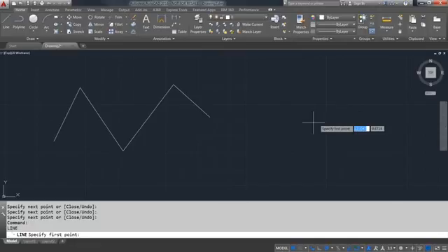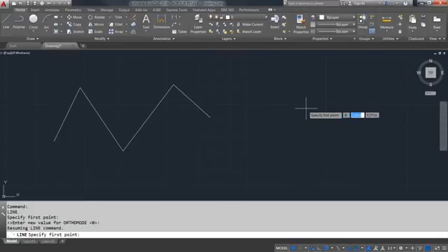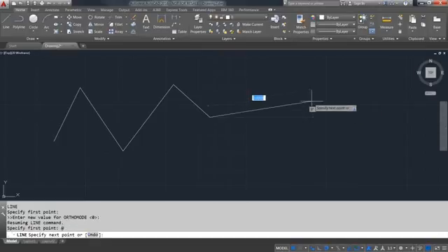series from. Now, I can use object snaps too, and that's what that green box is there. I'm going to snap the start of my next line to the end of the last line. Now, I don't have to necessarily use object snaps if I want to start at the same place that I left off. The last one, a little shortcut here, is you can put in the @ symbol and press enter, and it will automatically place your first vertex at the last vertex that you placed in your drawing.